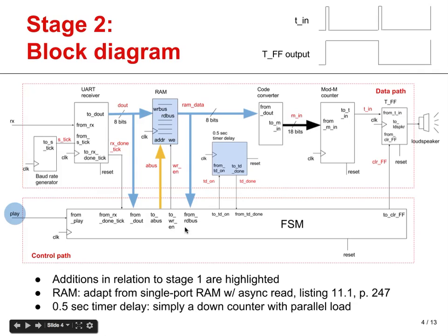Now likewise, for every output that goes from the control path into the data path, there will be one or more state boxes or conditional output boxes. So once again, if after you have generated your ASMD chart, you find out that one or more of the outputs that are represented here are not shown in any of these state boxes or conditional output boxes, then something is wrong. You have either forgotten to use any given output, or you had represented outputs that weren't really necessary.